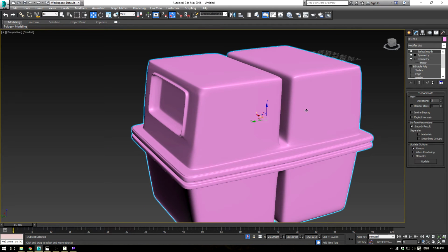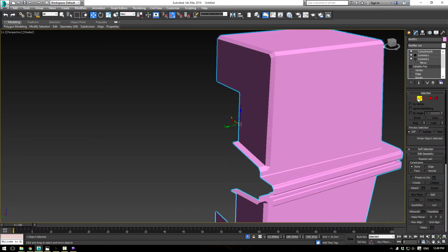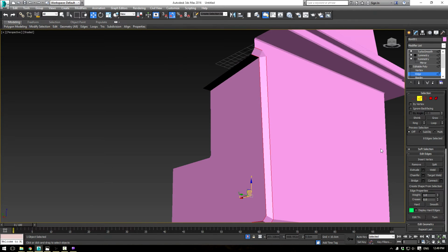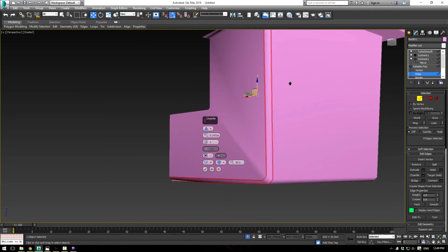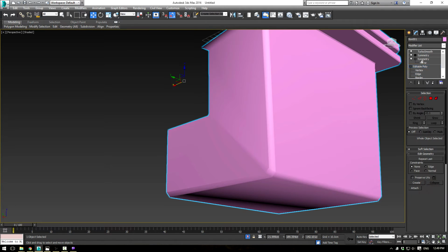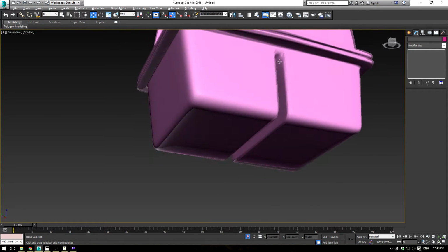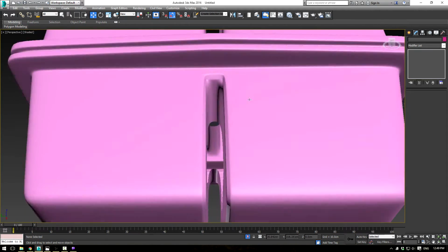Well, I think we might need to harden our chamfers off a little bit. So let's go back here into the edges, and let's chamfer those edges that we chamfered. I think we missed one here. There we go, and just chamfer them by a little bit. Oops. So what that should enable us is a harder edge there along the outside, which is sort of what we're after. Okay, something like that.